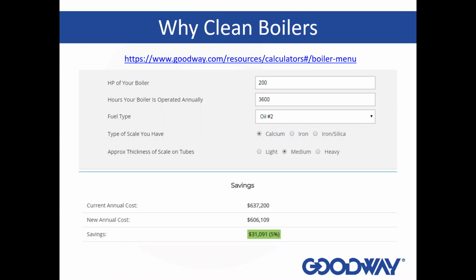Now, conversely, on a fire tube boiler you get the same type of effect, but in the water jacket. You're having the fallout of minerals on the outside of the tubes, and the fire is in the tubes, hence a fire tube boiler. So your heat is coming from the inside of those tubes into the water jacket, where you're producing steam. There are two problems occurring there.